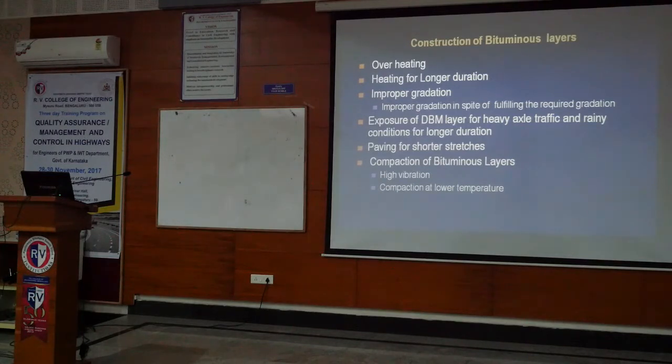And early raveling and all such things happen. Raveling, and overheating is that. Heating for long duration is also dangerous. In the sense, the mix is heated for a long duration, it's in the drum for a long time. It should be unloaded immediately once the mixing is over.